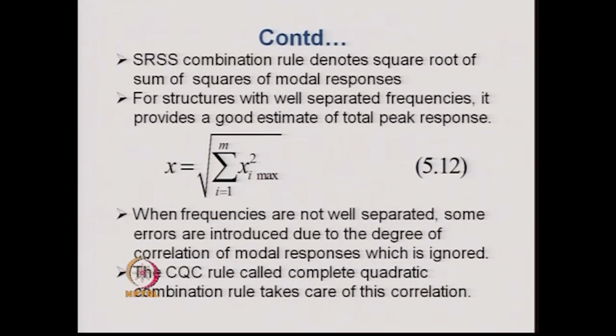The next rule is the SRSS combination rule, which denotes the square root of sum of squares of modal responses.